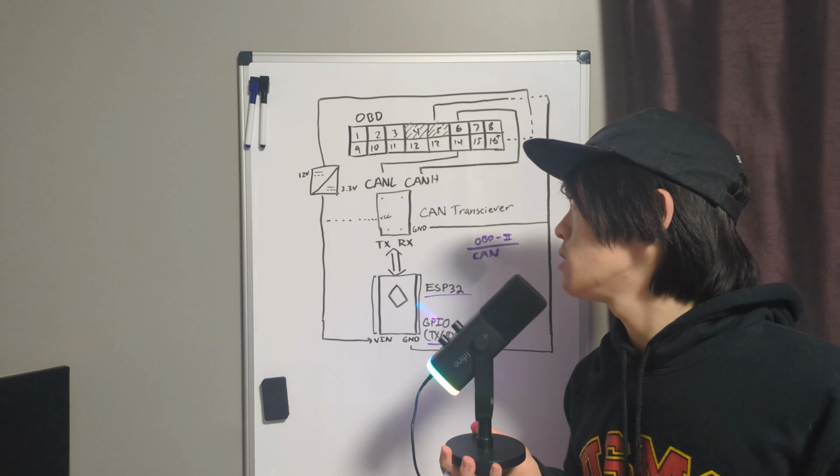The other parts start here, like a buck converter, and pins 4 and 5, these are just different parts of the electrical system, right? Because they all need electricity to function. Pin 16, for example, outputs the 12 volts from your car battery. Pins 4 and 5 are ground pins, which will connect all the other components that need to go to ground. And pin 16, the 12 volts, can provide power for all this. So it should be able to operate within the vehicle without needing any external power supply. And so now, I'm going to get to designing it.